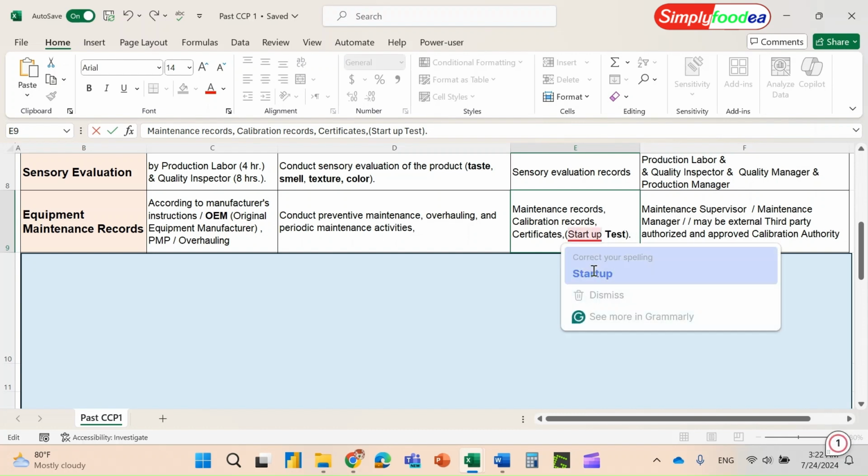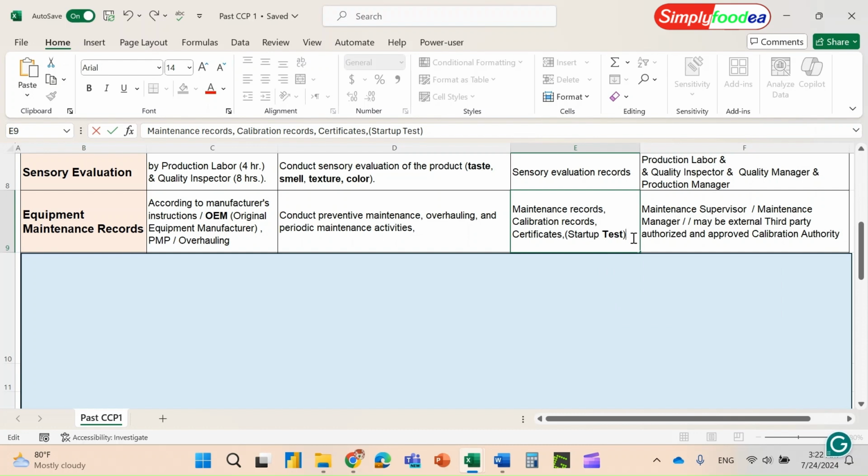And of course, a very important thing after the maintenance is the cleaning. We mentioned it, the startup cleaning, because maybe there are traces of grease, maybe lost nails, whatever the physical hazard, maybe tools, maybe gloves, anything related to the overhauling, maybe the wooden box in which you were storing the machine or the spare parts. So all these parts are very important.